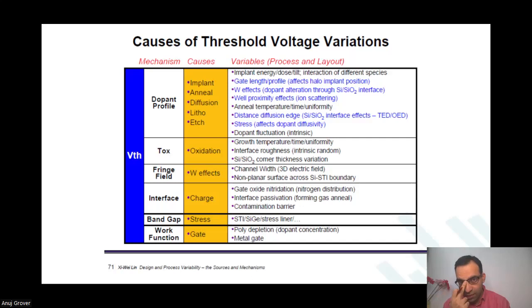Or there is some IR drop that happened, let us say. Everything was the same, but due to a 20 millivolt IR drop, now the VGS that you observe is a little different. Those are pseudo variations. Again, you cannot say what will happen. They are dependent on some patterns, how you will run the device, how the user will activate the device, and so on.